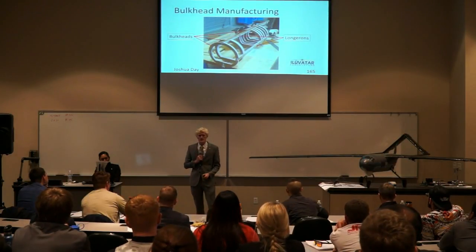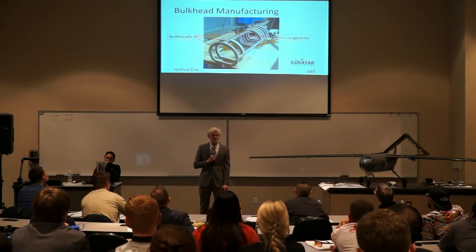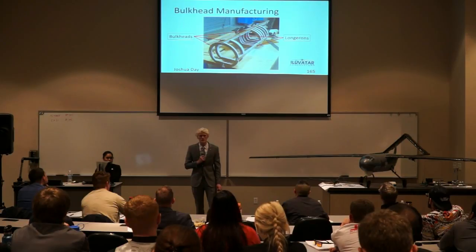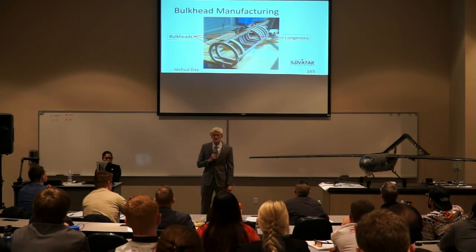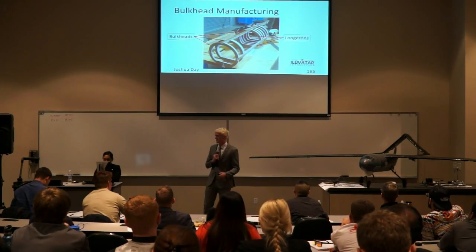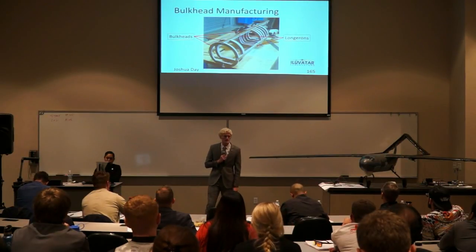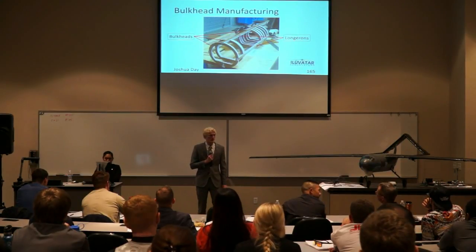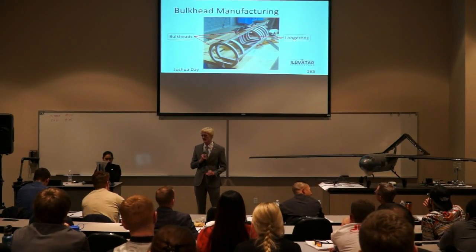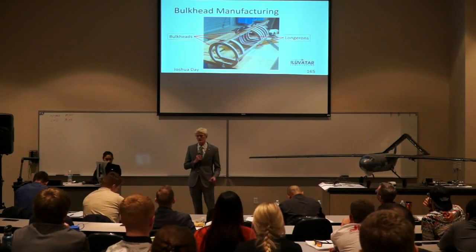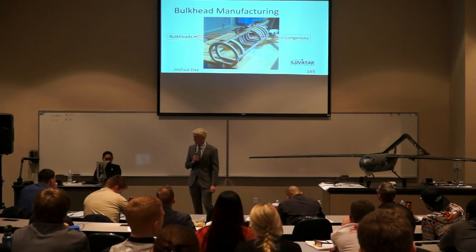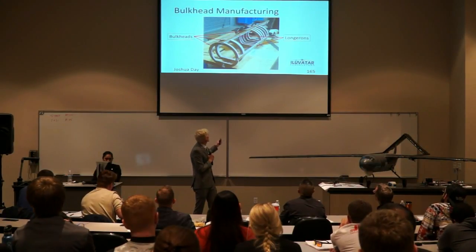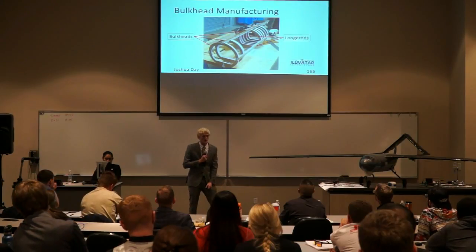To make the bulkheads, we created foam sections and cut those out using a hot wire, and then we created a large sheet of 2-ply e-glass and cut the bulkhead shapes as well as the longeron shapes from that using the water jet cutter. And then we epoxied those onto the foam, and we sanded down the e-glass and the foam in order to make them all fit together nicely. We then epoxied the longerons onto the bulkheads at their correct locations to make the fuselage shape.